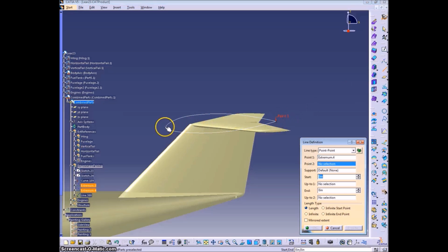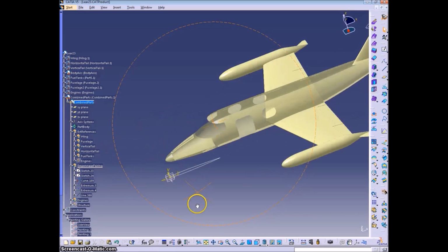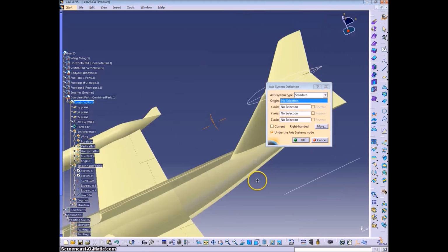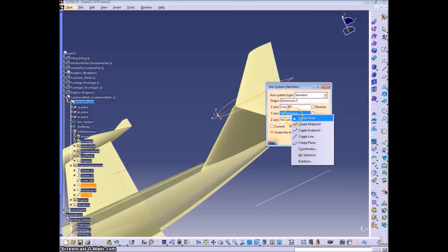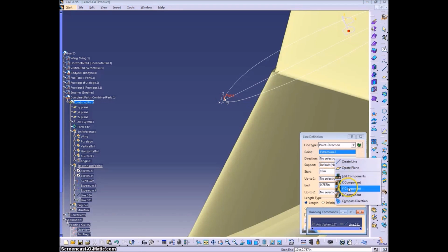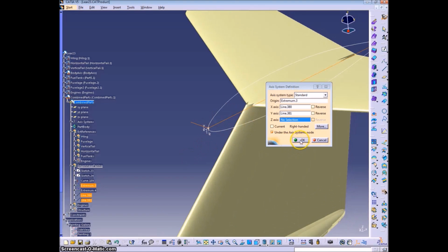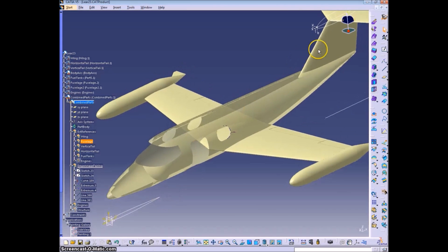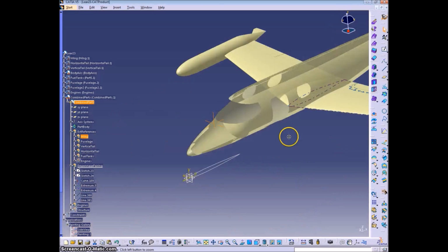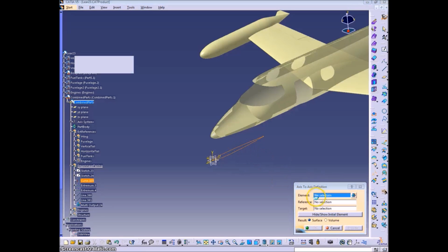To do that, we need to draw where our x-axis would be, since it's not the standard x-axis. You press the little axis button in the bottom right corner, and you can select what your axis orientations are. I'm just going to add a point with a direction to get the y component, because the y component is the same. So that creates little axes you can see there, x, y, z. Reverse the coordinates there so it's more aligned with the standard axes. And do the same thing here.